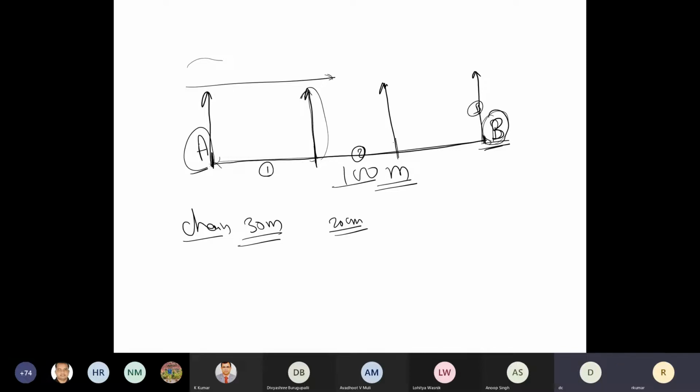If it is not falling on the line joining A and B, you can move it either left or right of the line, to be placed by the holder, so that A, B, and this first one come in line. Once these three are in line, the next ranging rod can be introduced at position 2, so that A, 1, B, and 2 are in a straight line by visually looking from A to B. Is it making sense? Yes, sir.